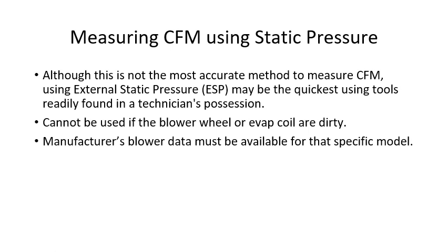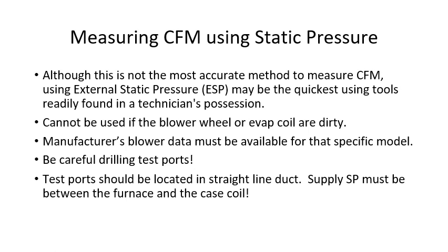The manufacturer's blower data must be available for that specific model. So it either needs to be in the installation manual that's there on site, or you may have to pull it up online. Be very careful about drilling test ports. If you drill a test port and you don't know what's behind it, you could cause damage to the system. Test ports should be located in a straight line duct as often as possible.